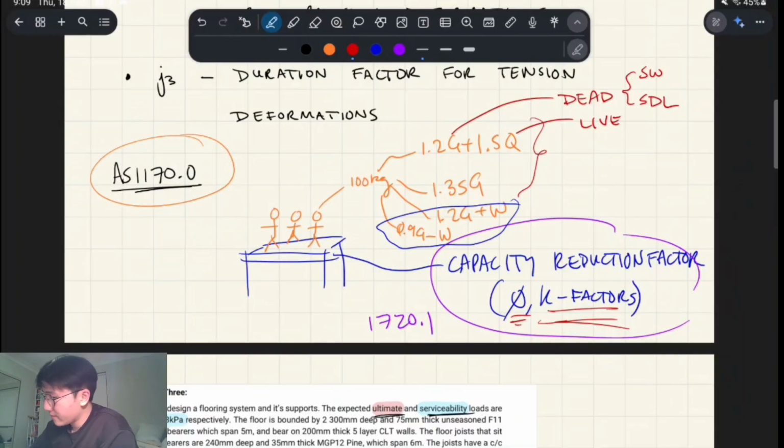So that's dead loads. Live loads are kind of like everyday loads. They're on and off loads, or loads which you'd maybe expect for a year, or it really depends. This is a pretty general category. You can include everything from pedestrian traffic to animals to snow. If you have an area which snows temporarily, that's a live load.